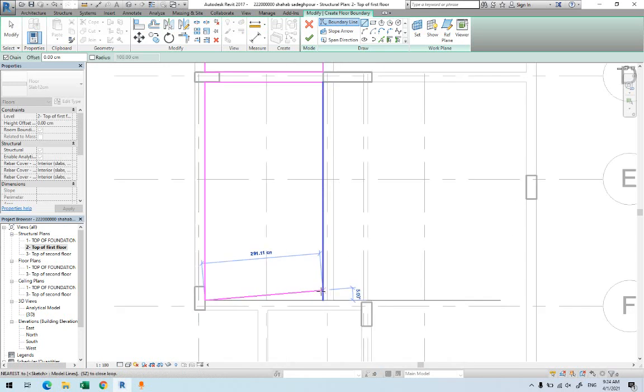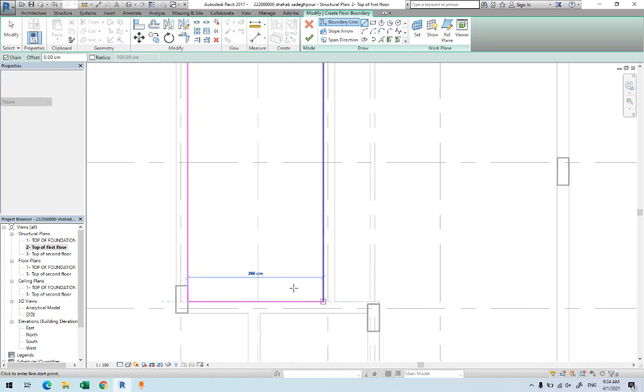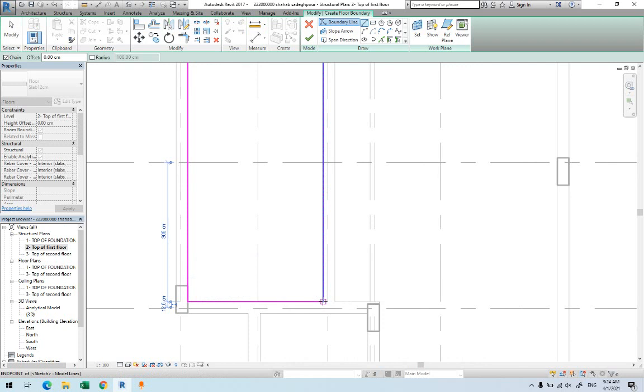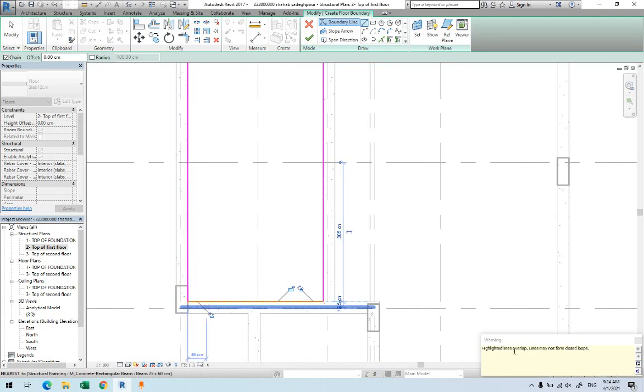They're not supposed to be any overlapping. What does overlapping mean? It means that if I have this one, yes, look, I came back here, it would directly close it. If I draw another line over here, like I'm trying to draw, if I draw another line over this line, Revit will give me a warning. It will tell me that there is an overlap. So it will tell you that there is something wrong there. This is one of the mistakes when you're using line. There will be overlapping. The other way is what? You have extra somewhere or no closing. If it does not close, also it's a problem. So it has to be a closed loop, no overlapping.